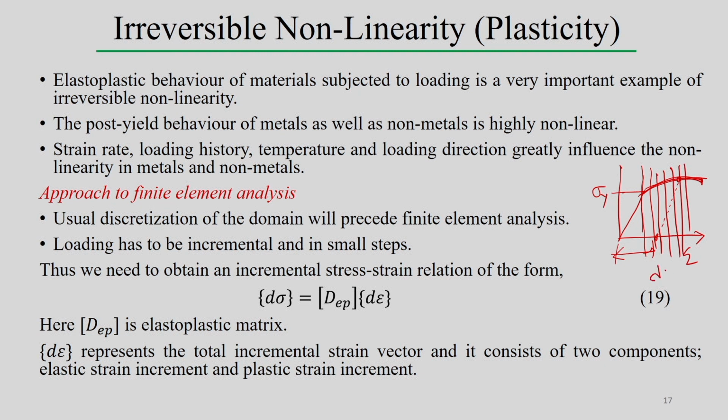Then we will look into what is happening within each small increment, how we can utilize the plasticity theory and different plasticity laws, and, for this small increment of the strain, what the update of the stress and the update of the displacement are. All of these can be updated in each and every step. That is the whole incremental mode analysis.